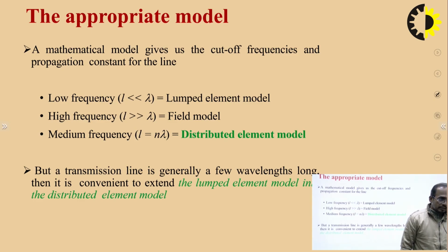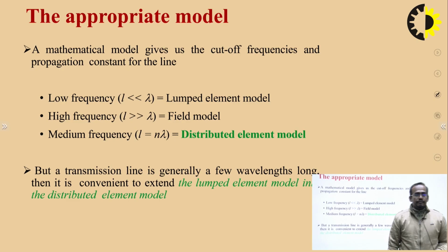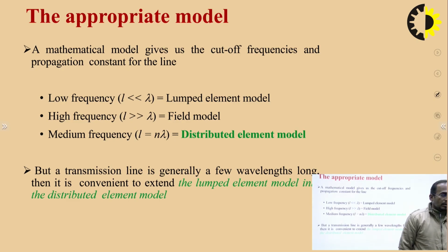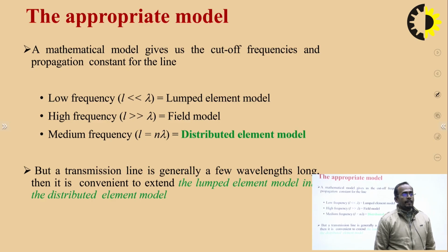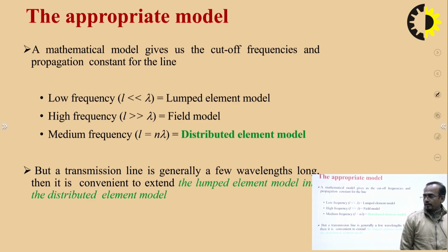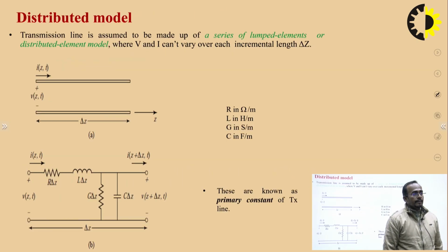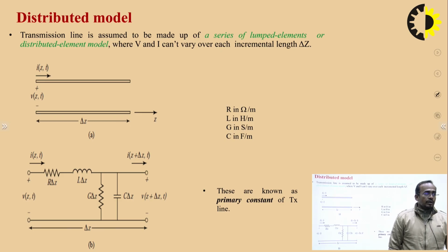But a transmission line is generally a few wavelengths long, so it is convenient to extend the lumped element model into the distributed element model. By using this distributed model we can analyze the transmission line very well. This is the distributed model.